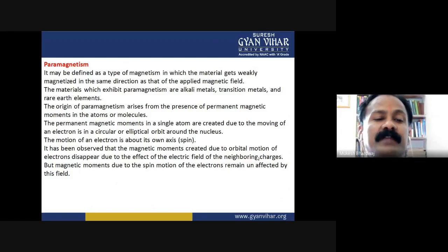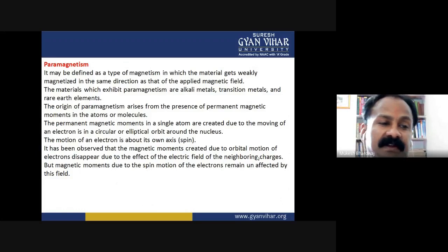When the individual dipoles do not interact with each other and are randomly distributed in the absence of the field, paramagnetism arises. In the other three magnetic behaviors, there is sufficient interaction between neighboring dipoles. If the interaction leads to the parallel alignment of neighboring magnetic moments, ferromagnetic behavior is exhibited. In case the result is an anti-parallel spin arrangement,